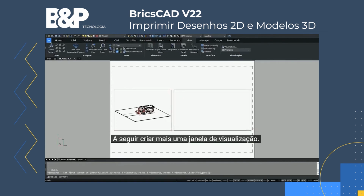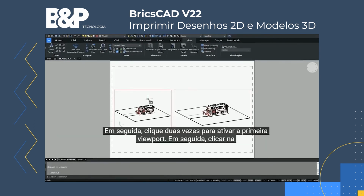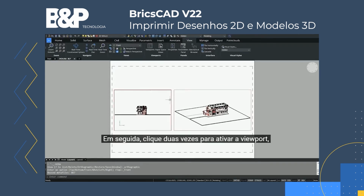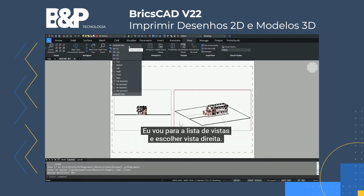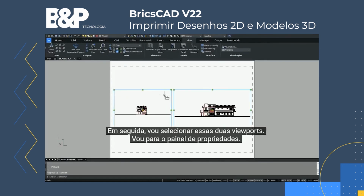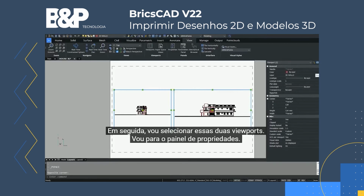Then I'll create one more viewport. Then double click to activate the first viewport. Then I'll click on the view pop-up and I'll choose front view. Then double click to activate this viewport. I'll go to view pop-up and I'll choose right view. Then I'll select these two viewports.